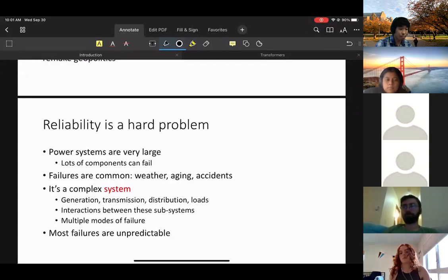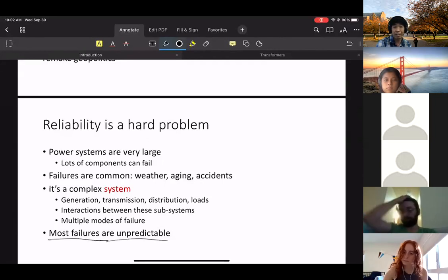And the system is quite complicated, okay, because it's so big, and because the physics is not easy to deal with, because the power flow equations are basically nonlinear. The system is complicated, and we don't really have a very good understanding of when this should work and when it should not. So what we have is a lot of unpredictable failures, meaning that nowadays when you see a failure, it's actually a surprise. Okay, it's something we haven't thought of before. Okay, so if a line fails, every year, we know how to deal with it. But nowadays, a lot of failures are ones we never anticipated, and it's hard for operators to deal with them very quickly.